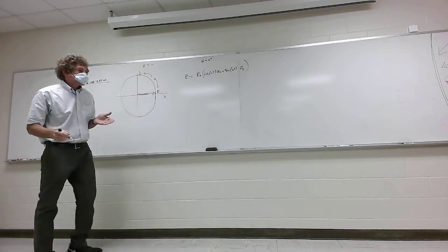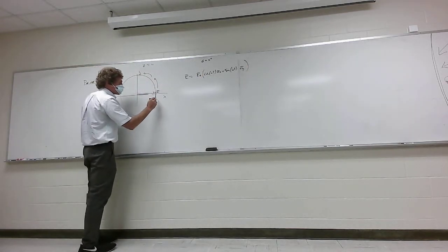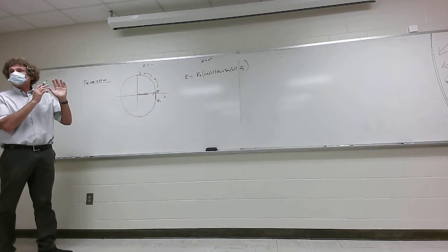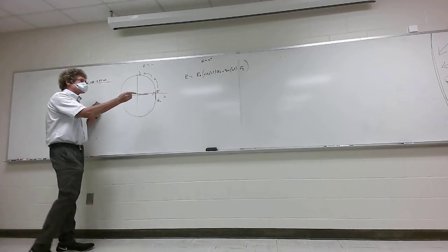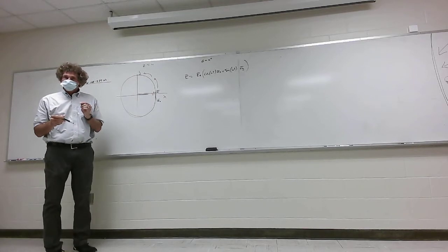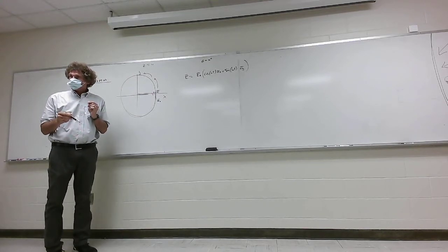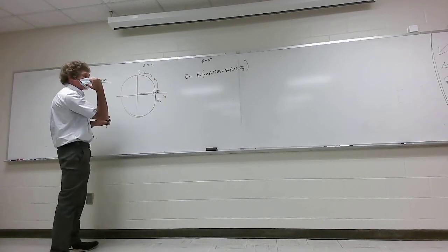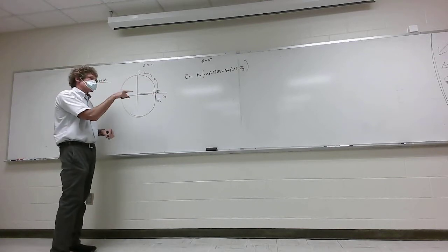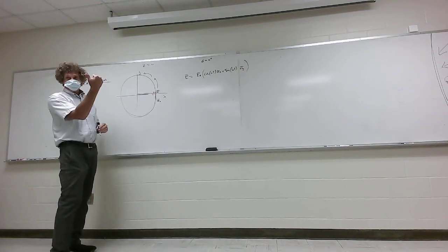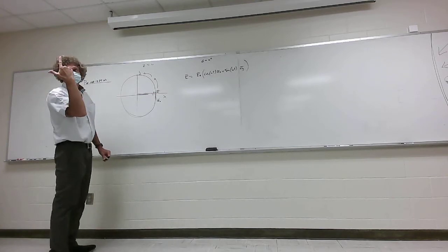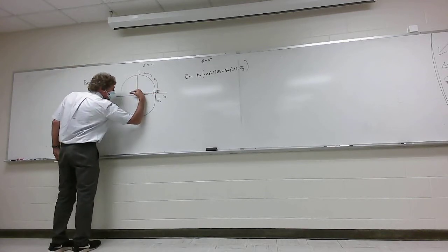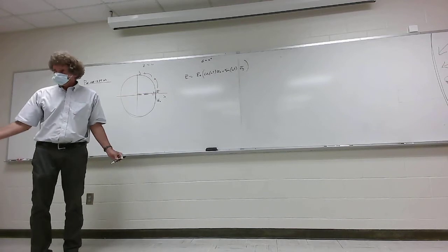Now, just take a look at that and see if that makes sense. This is just one of, by the way, you can describe this mathematically in a whole bunch of different ways, but they all do the same thing. They trace the tip of this field vector versus time. I've got it going in the counterclockwise direction, don't I, class? And if you have a right hand, and you take your thumb and point in the direction of propagation, I'm saying the waves go in the positive z direction. So if that's x, that's y, z's out of the board. Y'all follow me? Take your right hand, take your index finger on your right hand, make a pistol kind of deal. Put it in this direction, and if it goes this way, that's called right-hand circular polarization.